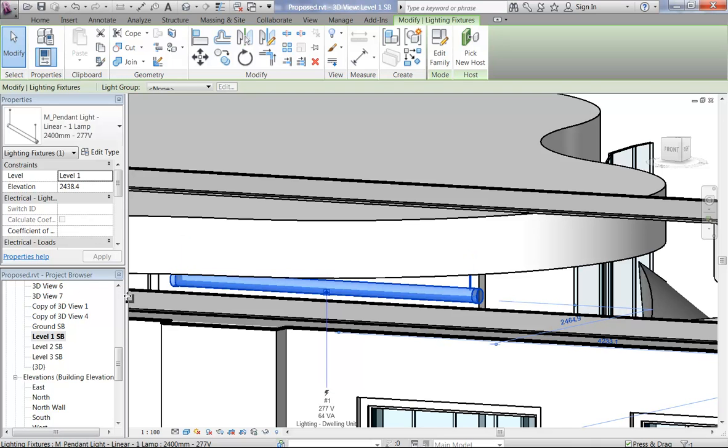But is it possible, for example, I know that you have the ceiling light and it says hosting in the ceiling. But is it possible to dehost it? Dehost it? Yeah, not really. You can if you go and change the family. So you go into the family, edit it, but not in the project.